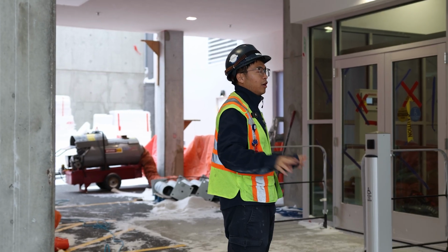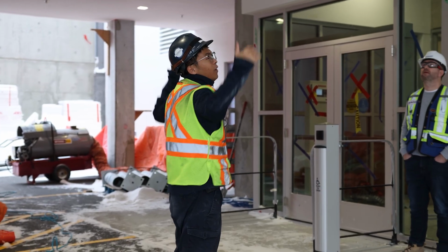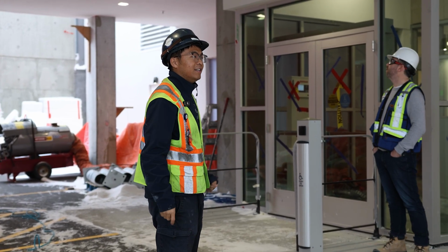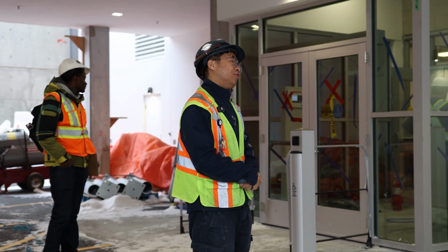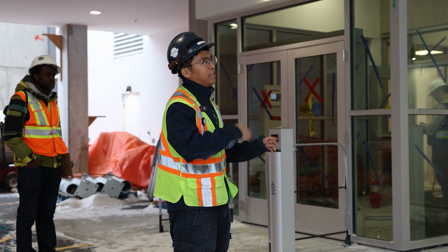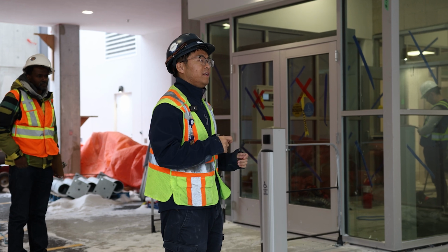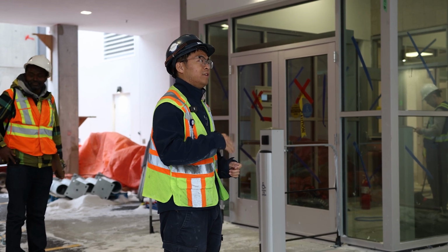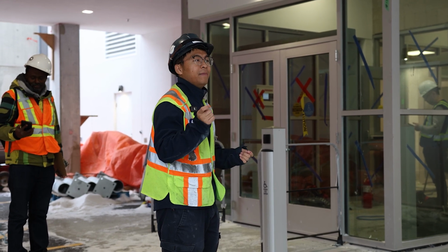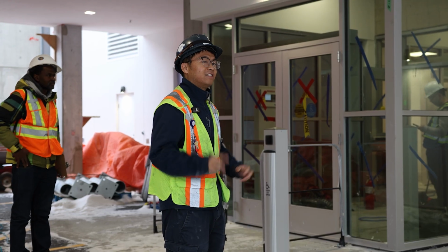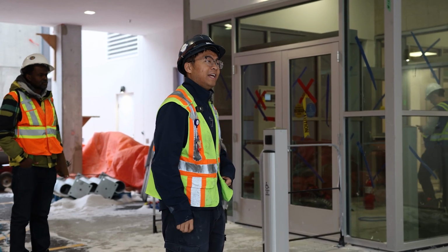It's all open. It's just pretty wide. That's why they put 4 units. You can change the space temperature set point for the soffit, but you can't adjust the heating demand for the electric heater. That's a fixed number.